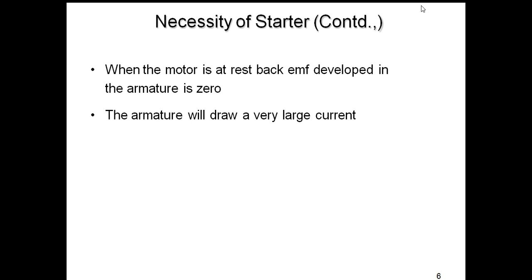As I have already said, when the motor is at rest, the back EMF developed in the armature is 0, because the speed is 0, and the armature will draw a very large current.